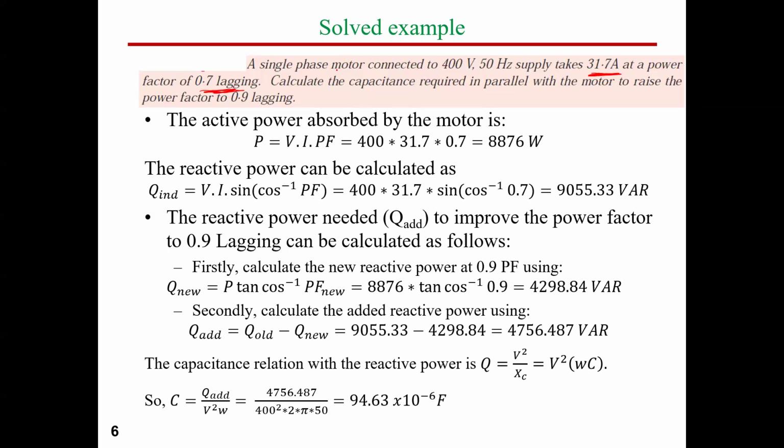The power factor of a synchronous motor can be controlled, and we will discuss that in the topics of synchronous motors. However, in general, guys, if you have any kind of undefined motor type, we can consider this AC motor as an induction motor, and we can consider this as a lagging power factor, or absorbing reactive power. Okay.